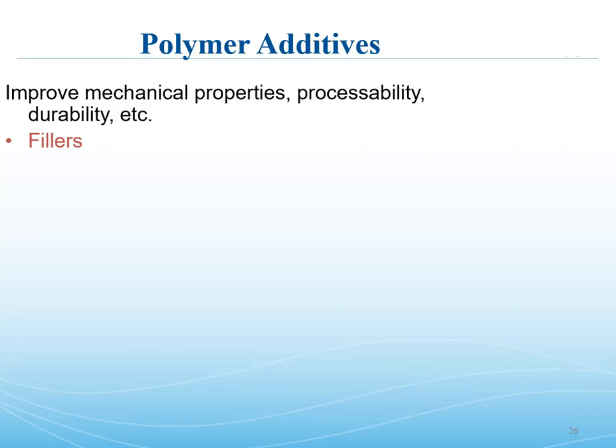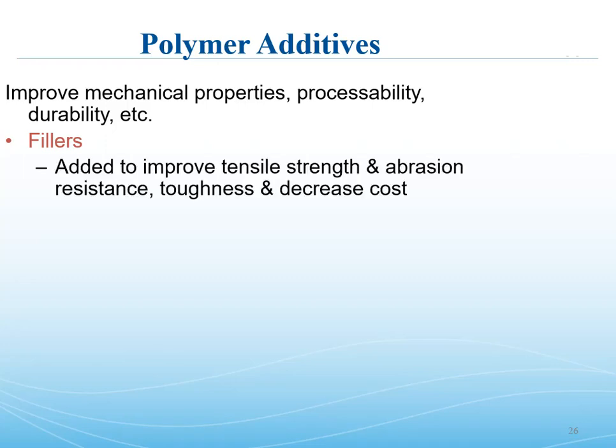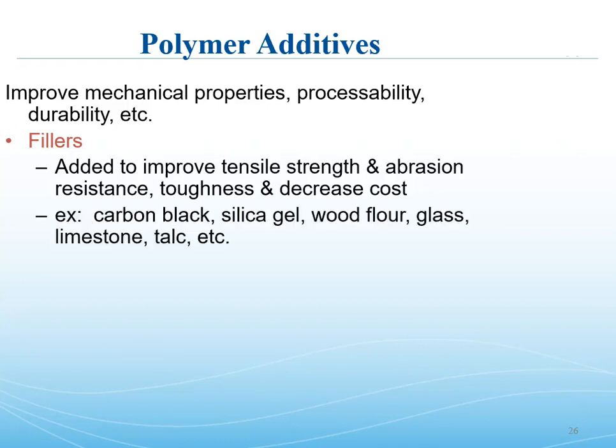Those kind of fall under the category of composites, particulate fillers. Those will add strength and sometimes toughness. In some cases they are actually added to decrease cost. A lot of inorganic mineral fillers are very, very cheap compared to the polymer binders that go between them and hold them together. But on the other hand, if it improves the properties you need and you can save money at the same time, you know, win-win. So you have some very strong stuff and some less strong stuff there. Some of these would be added for other reasons than just strength.